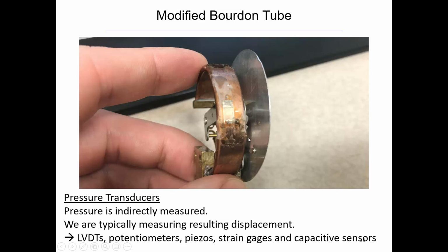One way would be to attach a strain gauge on here. We just learned about strain gauges. That's what this is. In our last lab, number 10, this is what you would be doing. And that lab has a lot of technical skills in cleaning off this Bourdon tube, not only getting off all the gunk, but using rubbing alcohol to remove the oils from fingertips, stuff like that. And then we adhere, using super glue, a strain gauge, that's this, down onto the tube.